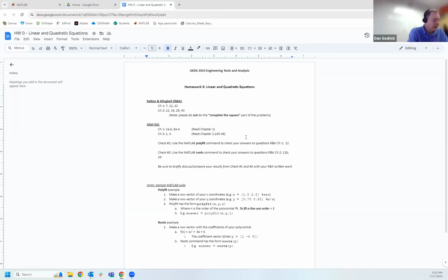So if we look at our data, we see that SM is actually our x data, and SA is actually our y data. And so if we use our points and use our tool, we can find y, SA, as a function of x, SM, and then we can just know that SE is our intercept and SE over SUT is our slope. So that's how to approach it.